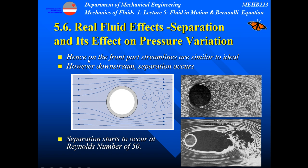Hence, on the front part, streamlines are similar to ideal. So here is similar to ideal. However, downstream, meaning after the obstruction here, is the separation point. So separation starts to occur. When separation starts to occur, you will no longer see the similar ideal streamline here.